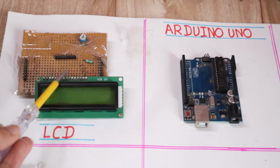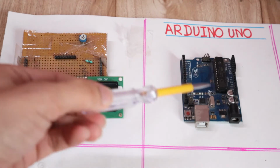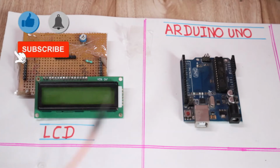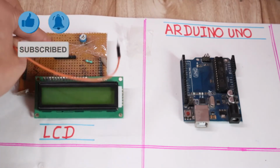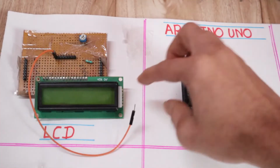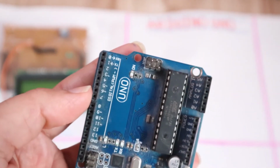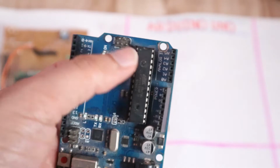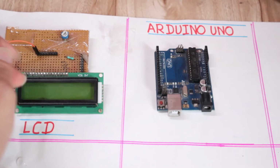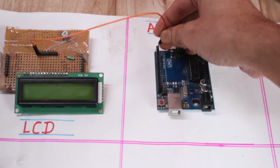Once you create this circuit on a zero PCB or on a breadboard, now we will connect it pin by pin to the Arduino. The first pin we have to connect is the RS pin of the LCD, and this should be connected to pin number 2 of Arduino. You can see on Arduino there is a pin number, so we can easily connect as per the program. The program explanation we will see later, but first connect the RS pin of the LCD to pin 2 of Arduino.